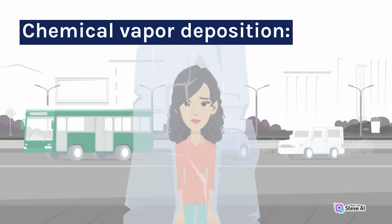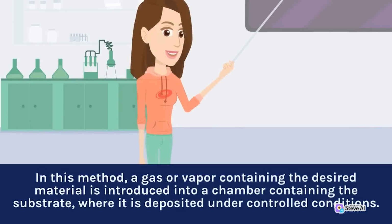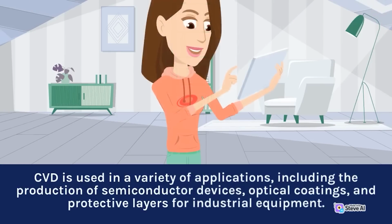Chemical vapor deposition. Chemical vapor deposition, CVD, is a process used to create thin films of material on a substrate. In this method, a gas or vapor containing the desired material is introduced into a chamber containing the substrate, where it is deposited under controlled conditions. CVD is used in a variety of applications, including the production of semiconductor devices, optical coatings, and protective layers for industrial equipment.